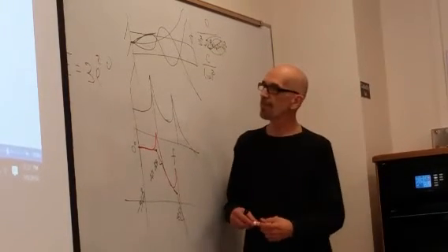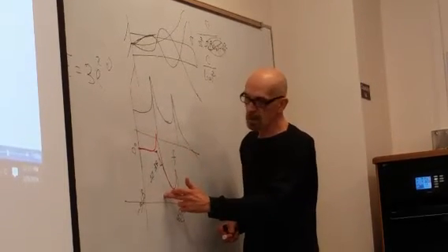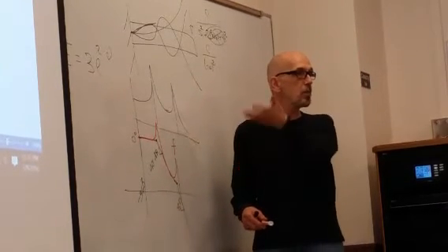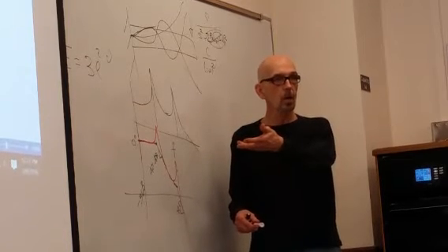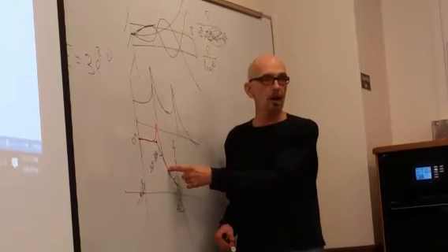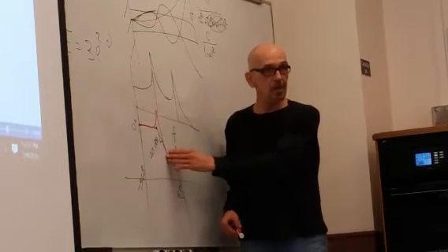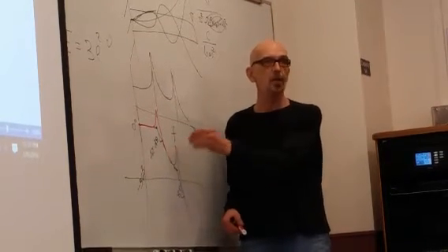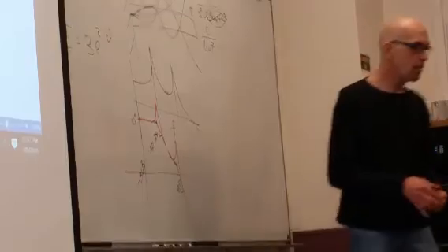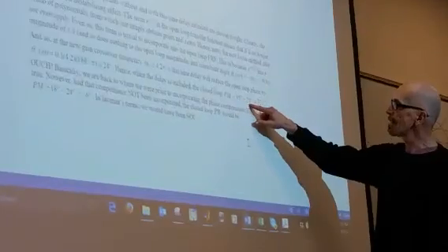Okay? So if you have a phase, say, at gain crossover here at minus 150, that means you have a 30-degree phase margin, right? You're 30 degrees above negative 180 at the gain crossover. Well, what happens with that time delay? You take the omega times the time delay 0.1, and it may drop it by 30 degrees. Because only the phase changes. The magnitude at that crossover doesn't change. e to the i omega t has magnitude 1. So this is what happened. The time delay dropped the phase margin back down to 21 degrees.